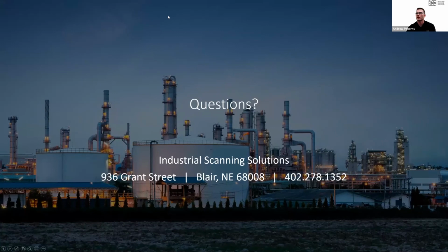From Eaton: what might be the turnaround time for a scanning project with, say, a house-sized building? House-sized building. Well, it's going to depend a little bit on the detail that you're trying to capture. If you're really trying to get in the nooks and crannies, that's going to require a little bit more. But typically, for generic house requirements, 1/8 inch kind of accuracy, to get in and scan it, I wouldn't expect to take more than 4 to 6 hours.